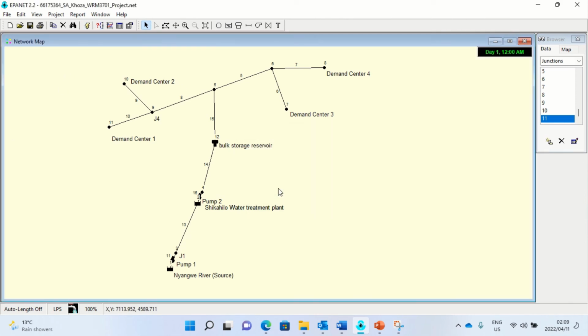See, it's still successful, but also before I obtained this, I came across errors where I had to increase my diameter, and I also had to change the coefficient of roughness, because some of my velocities were actually more than 1.5, which is the maximum which is required.